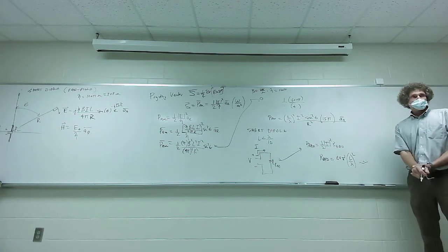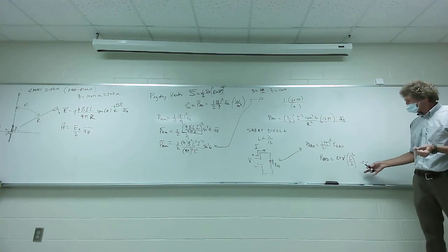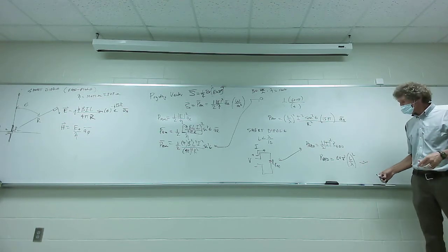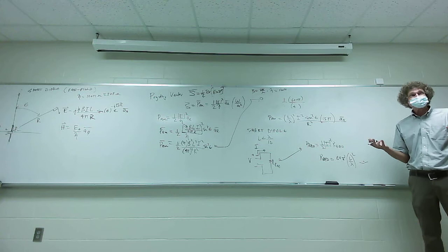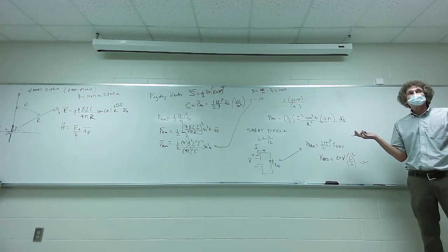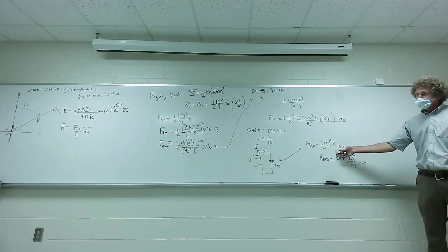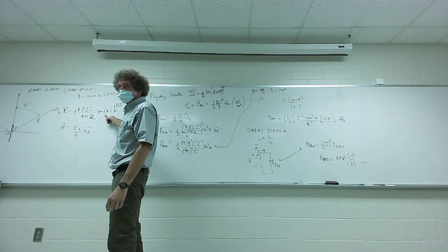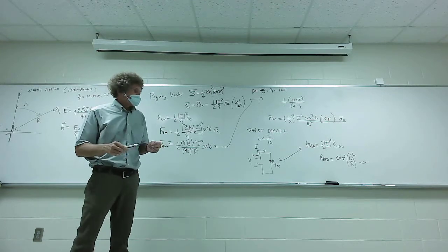Now here's where we're going with this. You haven't seen this yet. If I know for a given antenna that this is the radiation resistance if it's short, I can figure out for a given voltage how much power is radiated. I can figure out how much current flows, right? If you know the radiation resistance, theoretically you would divide it into the voltage, and you get the current. You with me on that, everybody? You got the current, you can find the power radiated, right? You got the current, you can also find the E field, can't you? See how it's proportional? Anyway, you can find the H field, and you can find the power density.